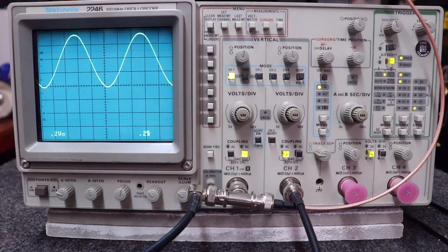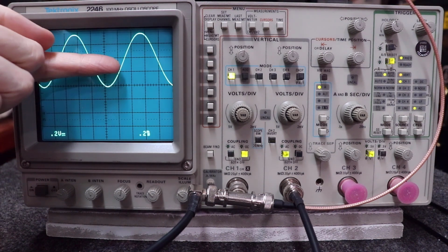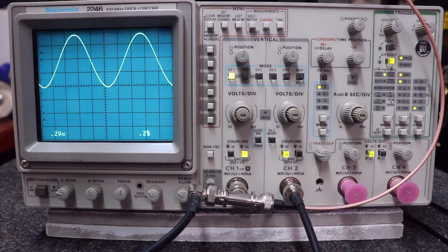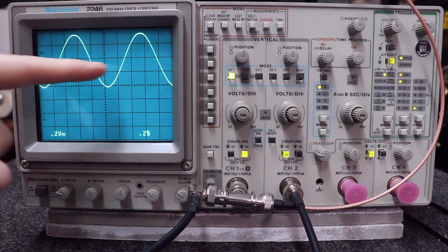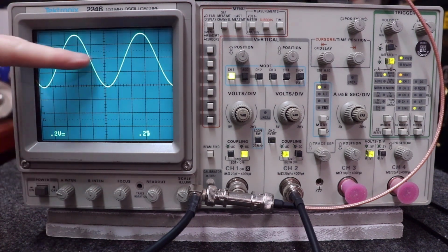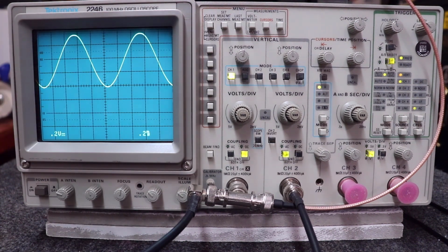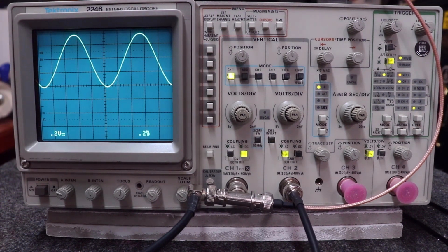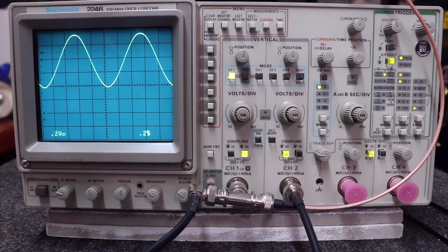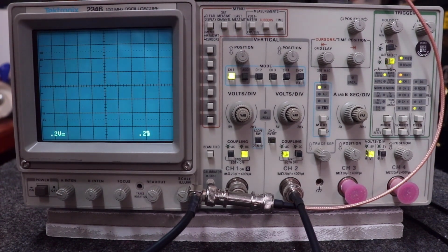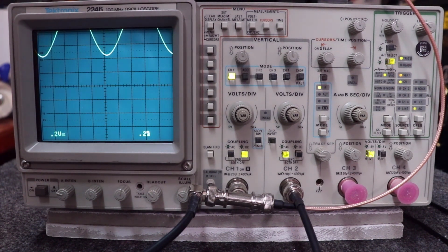DC voltage to my signal. Did you notice what happened? My signal rose up by the amount of DC that I applied to this signal. Okay, well that's good and grand. You can see, hey, my signal is riding on top of some DC component and it's moved up because of that. Well, what if your DC signal that it's riding on top of happens to be 200 volts? Woo! You just lost your signal and you're not going to find it. It's going to be way up there, okay?